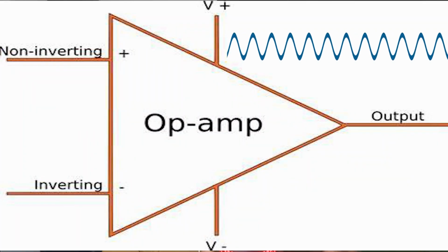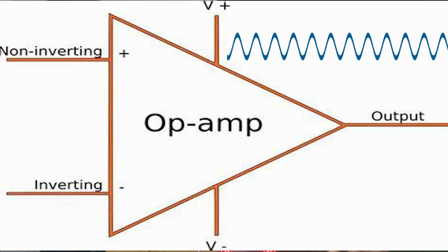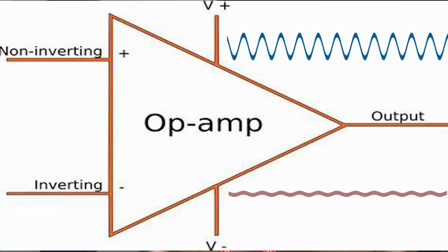Fortunately for you, the LM741 got your back. The ratio of the variation of the supply voltage compared to that of the output voltage is absolutely massive. So if the supply voltage varies around 100 millivolts, the output voltage will only vary around 10 microvolts, at most.